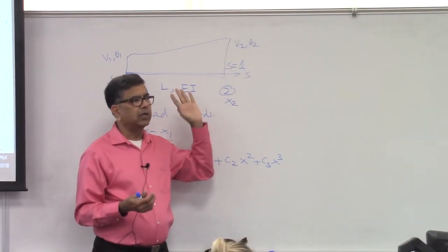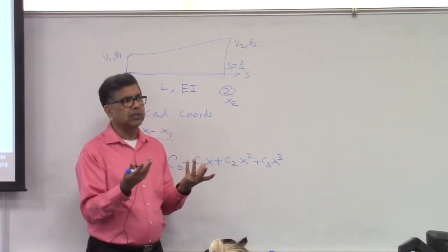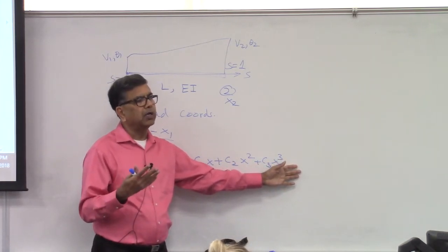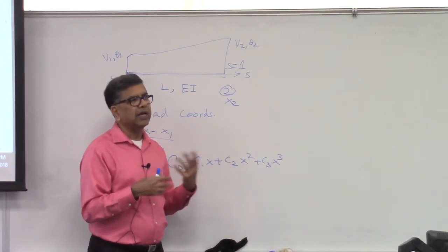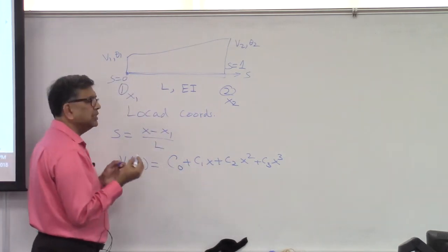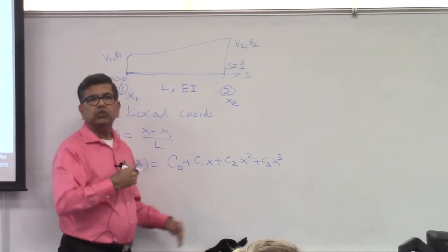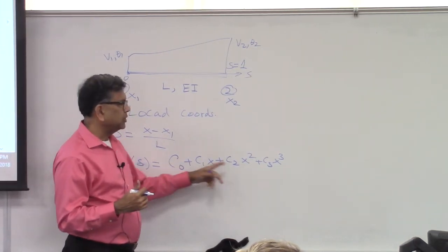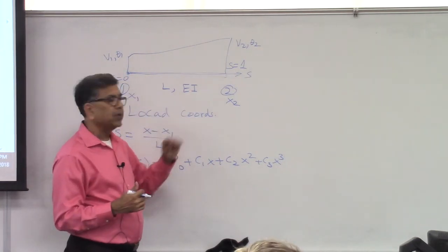The only way I can interpolate is by having 4 equations. If I have, like you said, a 4th order polynomial, it's called a quartic polynomial, there will be 5 constants, and I don't have the information. If I have less than that, then I have superfluous information, it won't work. So how do we evaluate the constants? So this is exactly like the Rayleigh-Ritz method. In the Rayleigh-Ritz method, you assume a polynomial, and then jump to calculate the strain energy, everything. Here we can't do it. We cannot use these arbitrary constants. We have to convert them into nodal degrees of freedom. How do we do that?